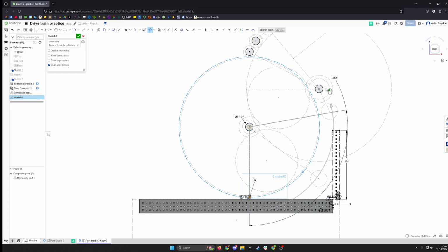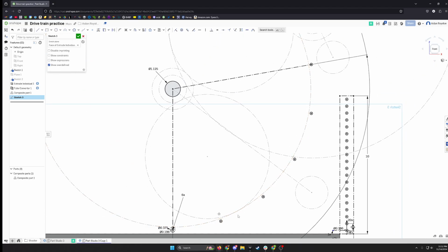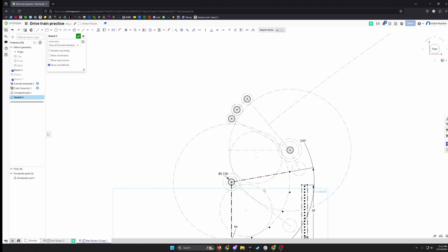So we've done that, and now we want there to be more than just 3 of them. So let's go ahead and double that to 6, and then just hit left click to confirm, and now we have 6 holes for our standoffs to go along perfectly. And so now we're going to go ahead and do the same thing up here, because we have this space that we need to cover as well.